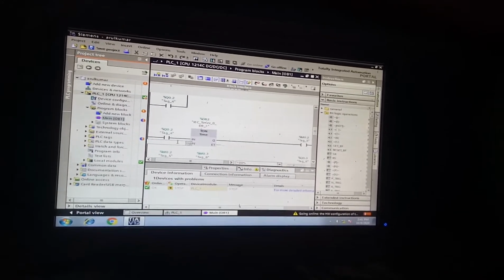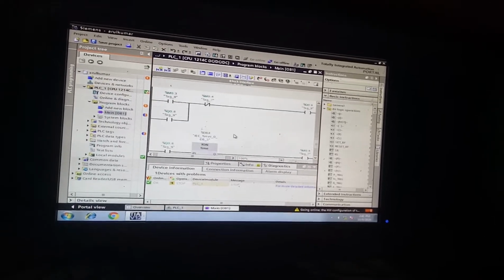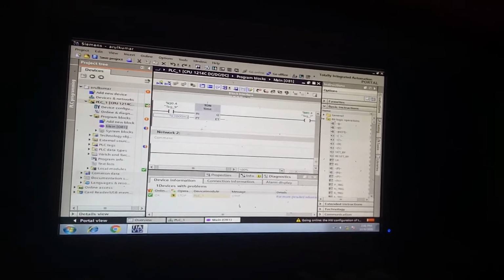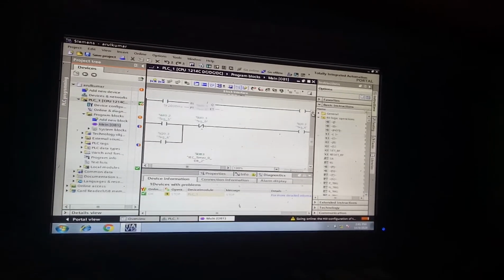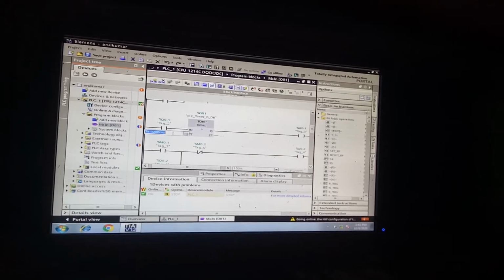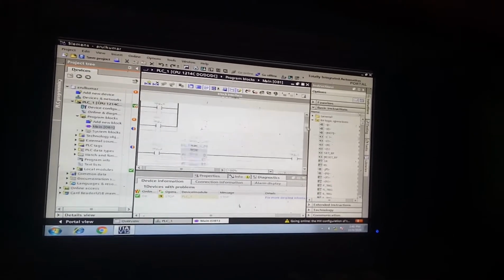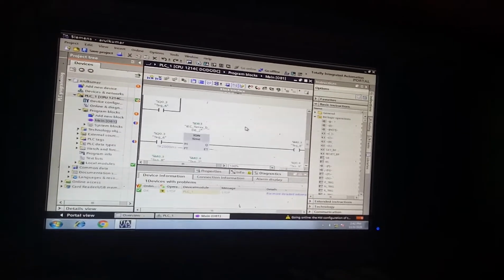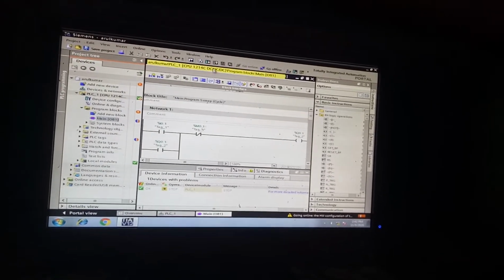So just click that. Here I go for 2000. This will be 3000. Here will be again 2000. This can be changed into 3000. Okay, so this way I assign the time values. After that we go for loading the program. So this is a program for two double acting cylinder continuous reciprocation. Okay, so I am going to load the program.